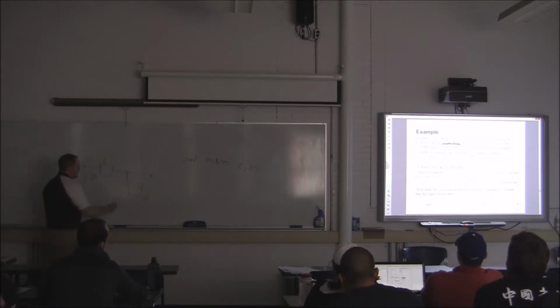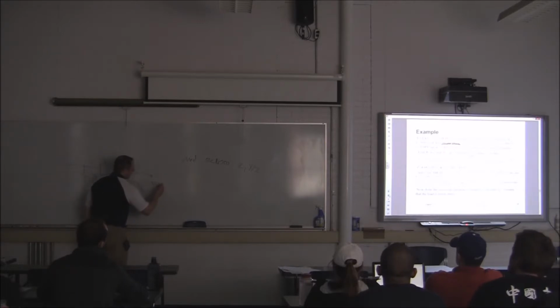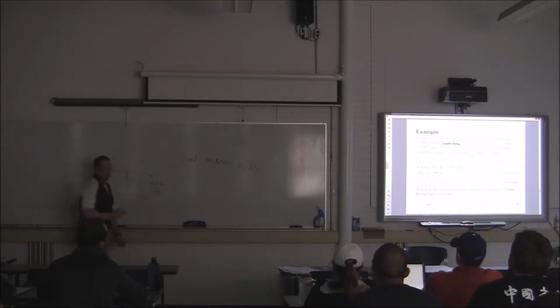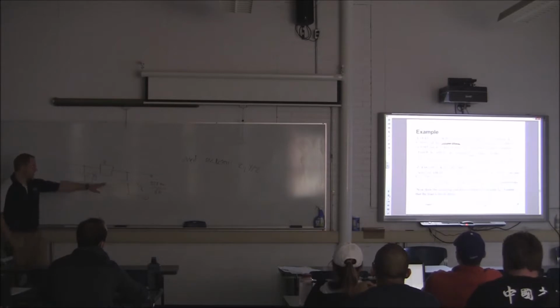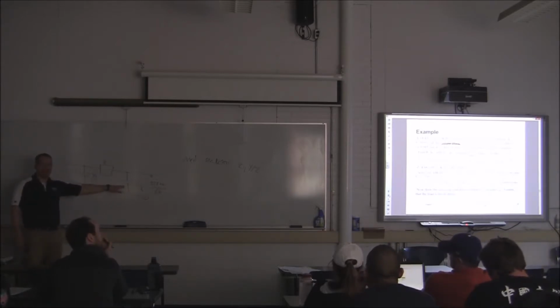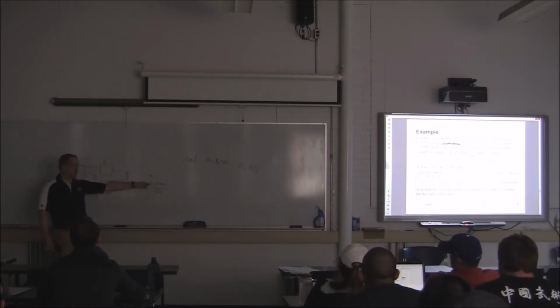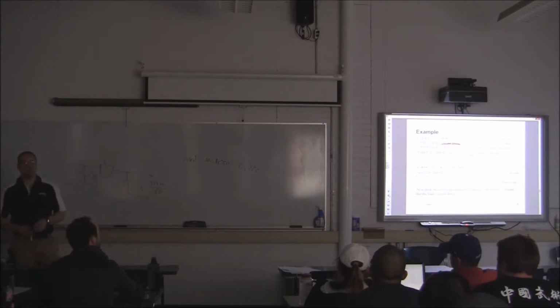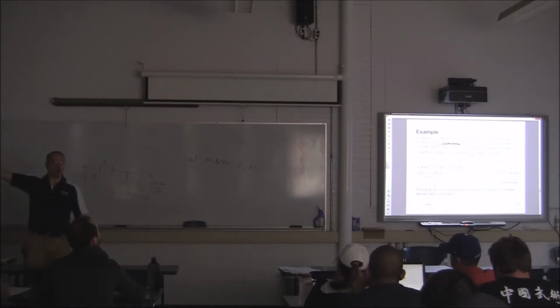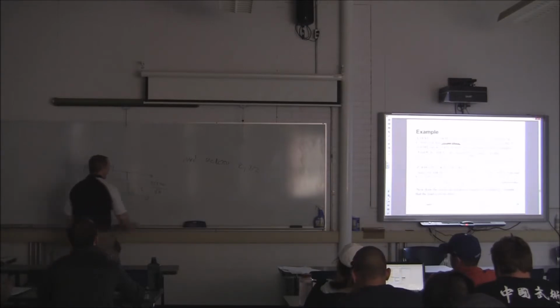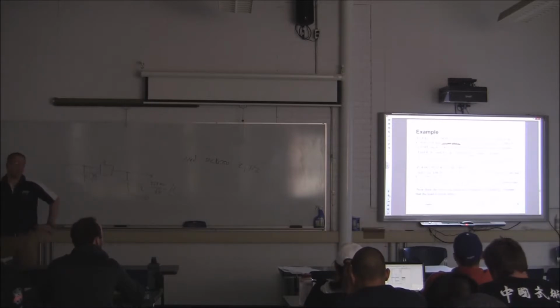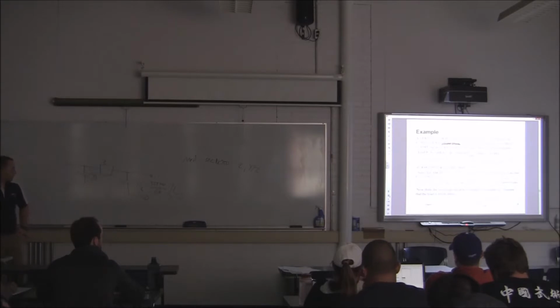Or is it 325 divided by the square root of 3? Remember, we have to work in phase quantities. This is a single phase capacitor. If I put 325, that would give me wonky results. So I have to convert that to a phase quantity, divide by square root of 3. And since there's no other point of reference, since this is the end of the line, let's make that 0 degrees. Got to start someplace. Let's put 0 at the receiving end.